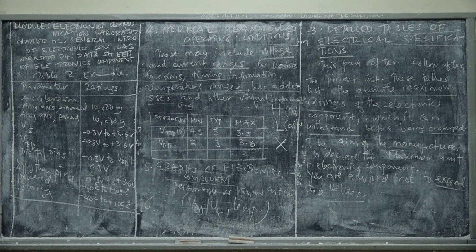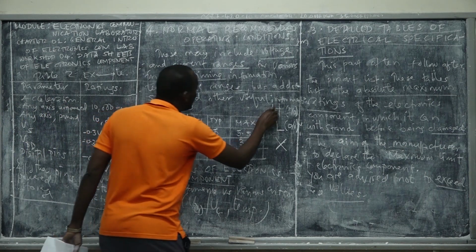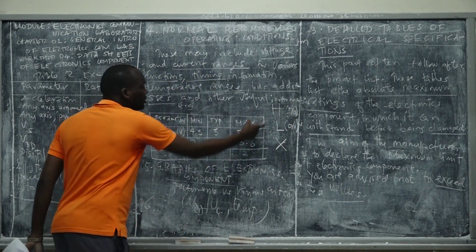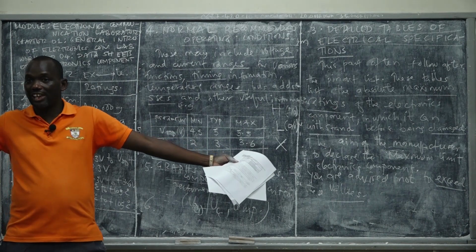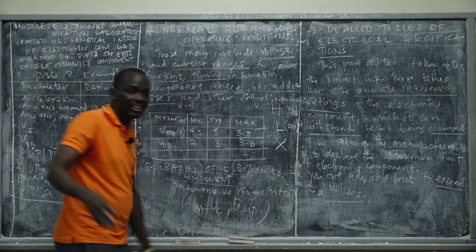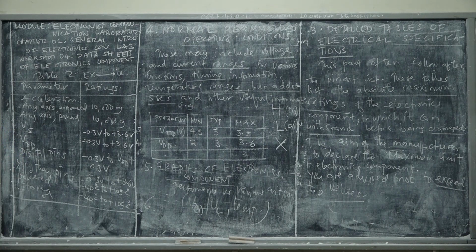That is good news. I know that you know low for 0 and high for 1, that is a good foundation. Today, update your mind: H can be 0 or 1, and low can be 1 or 0. It's just a matter of the manufacturer's decision. Why? There are some sensors that give high voltage when there is no signal sensed, and give 0 voltage when a signal is sensed by that sensor. Are we together?